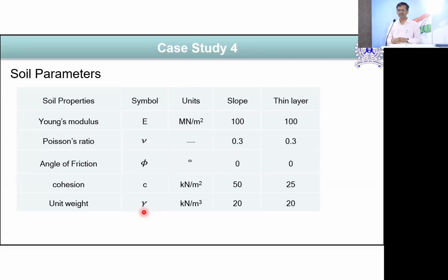Even the geophysical method is correlated with Young's modulus and Poisson's ratio. So if you are going for advanced numerical methods, you have to put in advanced parameters. Even they will ask for the angle of dilation, which Plaxis will add. If the angle of dilation is not known, some people take 5 to 30, 15 degree, 30 minus 15 degree, I mean random. So then comes, many times, the empirical method.